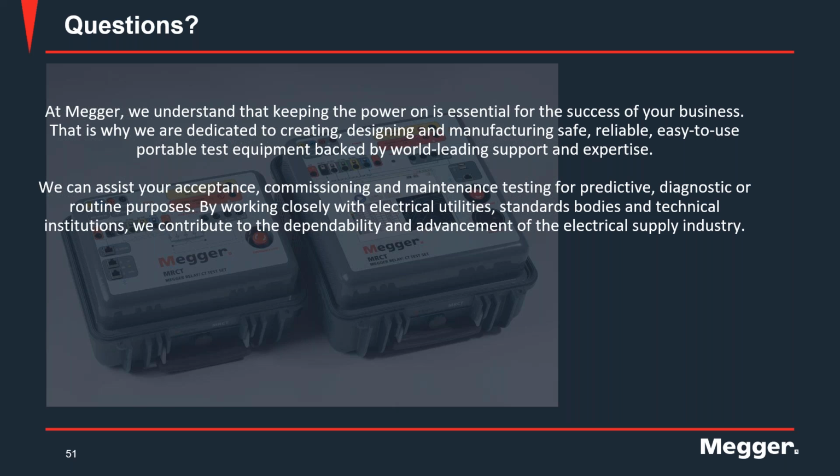A regular saturation curve has to have a linear section. Sanket showed a couple of slides, actually one from the IEEE, where you have the linear section, and then it has the knee point, and then it has the saturated section. So after that knee point.